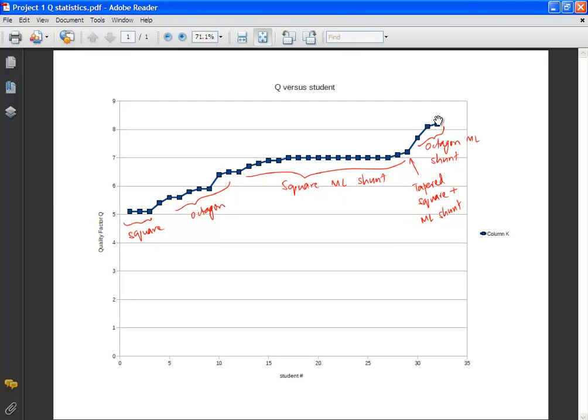So the ones from 7.7 to 8 are all using octagons, which we discussed, right? Octagons are much better, they have much better area efficiency. They're using multi-layers because in our case we decided to turn off the eddy current parameter, right? So your eddy current losses are much lower. What that means is you can go down to a lower metal layer and still end up getting a decent Q. Okay, it improves the Q, but it doesn't degrade the Q that much.